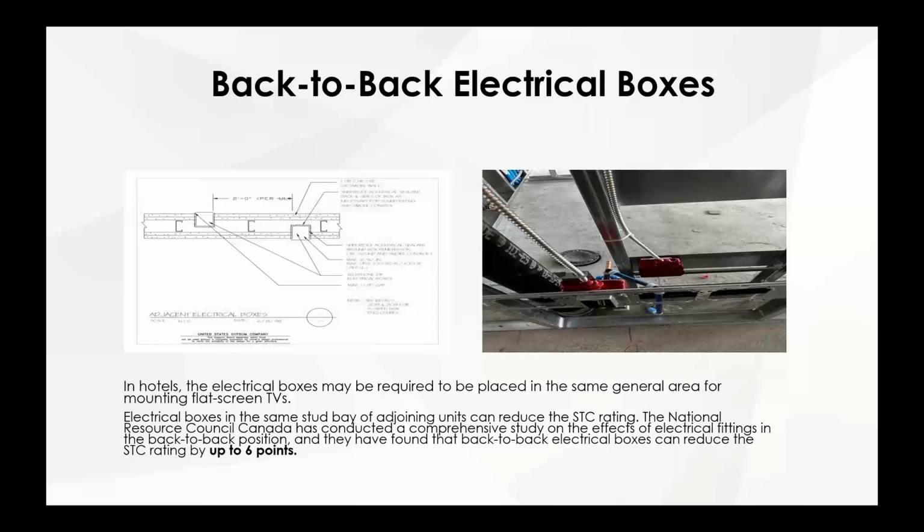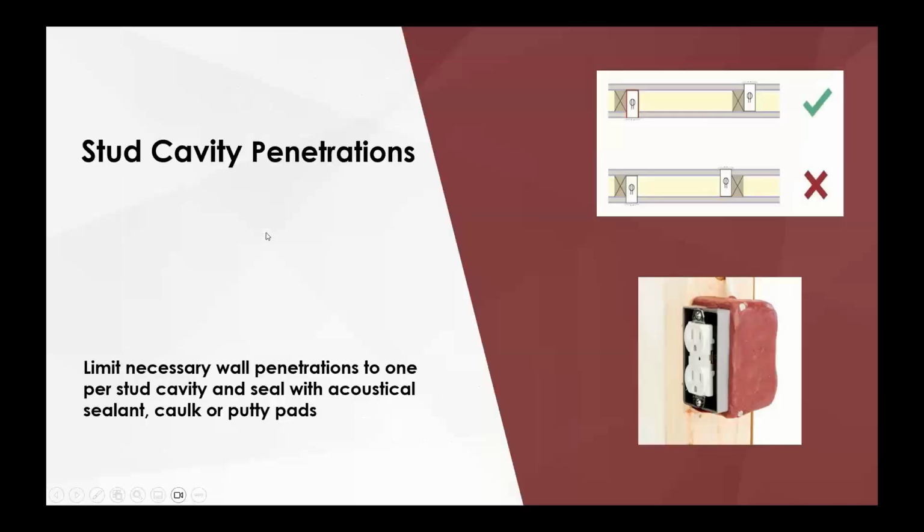Now, remember earlier when I was saying that the majority of the sound walls are also going to be fire rated. Okay, so this is typically what you want to see. You want to see the boxes in different stud bays for a fire rating. So keep that in mind. That's generally what you're going to see. Also here too.